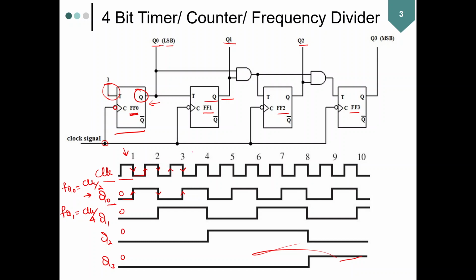Okay, so now we get to flip-flop 1. Flip-flop 1 has input from the output of flip-flop 0. The first negative edge of the clock cycle comes. Once this negative edge comes, flip-flop 0 makes a transition because its input was already set at 1. However, due to the delay in the transition, at this very moment when the input of flip-flop 1 is sampled, it was 0. The time it takes to transition from 0 to 1, during this interval it is considered 0.